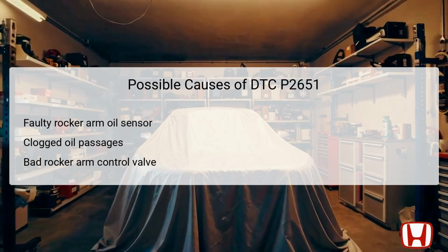Another possible cause is a malfunctioning rocker arm oil control valve, which manages the supply of oil to the rocker arms. Each of these components plays a vital role in ensuring proper oil pressure. So understanding these possible faults is essential for effective troubleshooting.